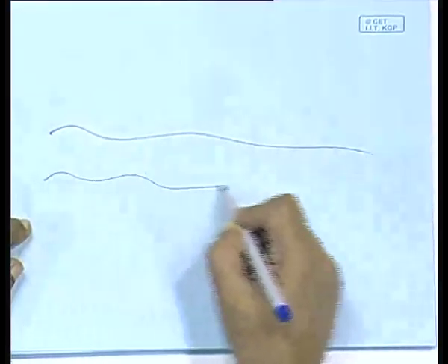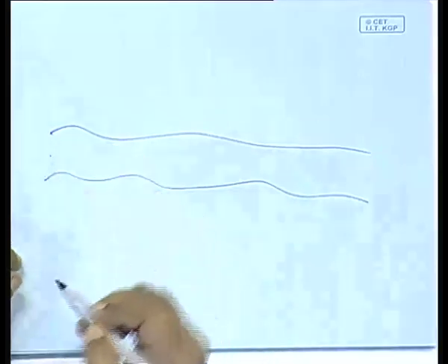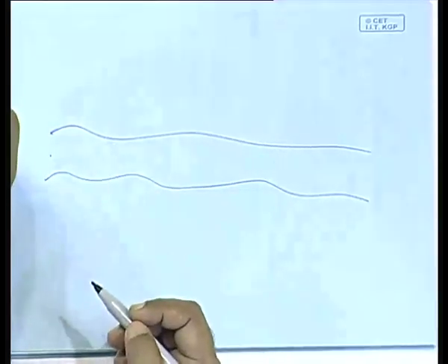There the method that is used is something like this. Remember this is applicable to turbulent flows. Somewhere you drop a bit of concentrated solution of some salt, and then it will mix with that water, and since it is turbulent, the mixing will be good, and downstream at some length. Say this is the river, here you are dropping that solution.